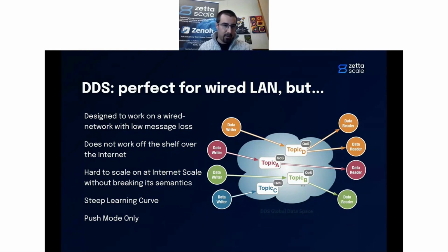And all of a sudden, DDS needs to publish all the discovery information for all the nodes, all the readers, all the writers that are in the robot into the Wi-Fi. This may cause some flooding of the Wi-Fi, which takes some time to recover, and the robot needs some time to recover connectivity with the rest of the building.